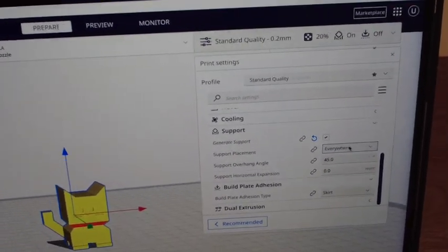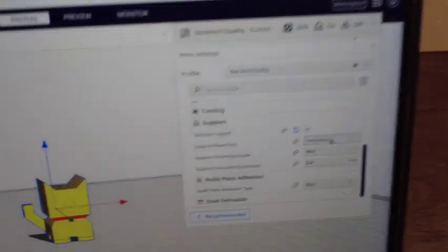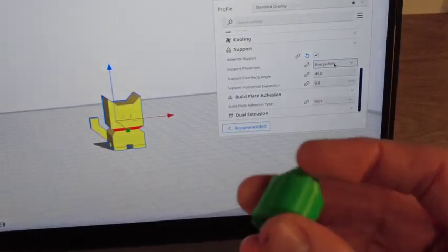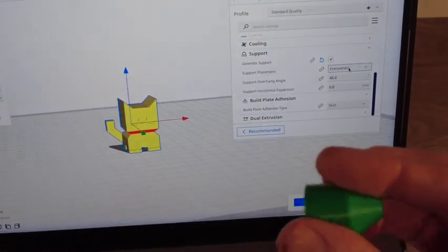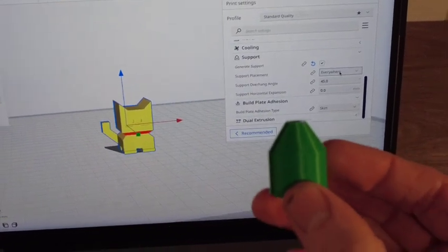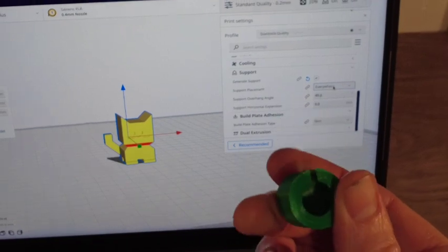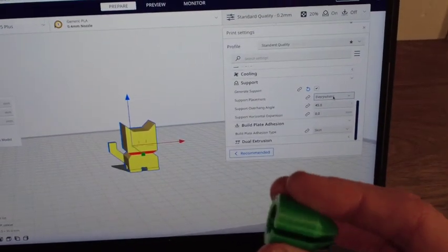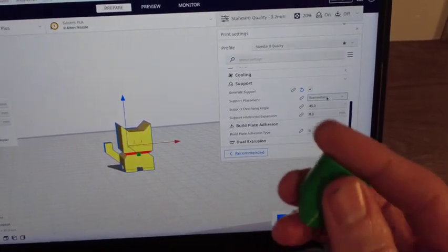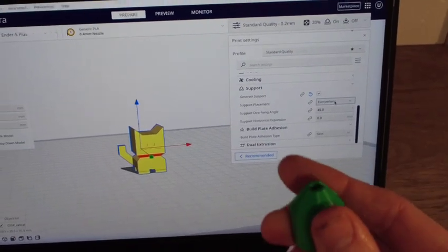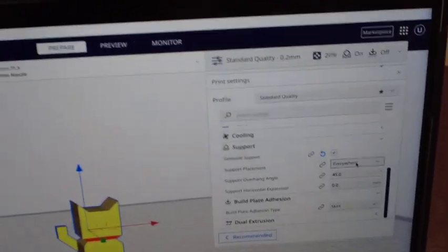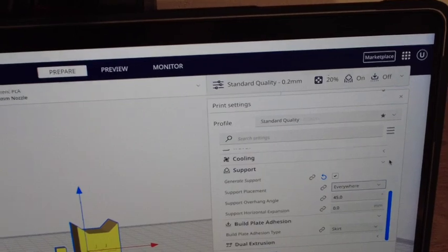So, if you feel like you need support, if it's something like I've just printed one of these, this to me doesn't need support. You can see how the printer's going to deal with that. It's going to be fine. But other things I have printed with support, just as an extra thing to prevent it failing, basically. So put that everywhere. So that's the support tab.